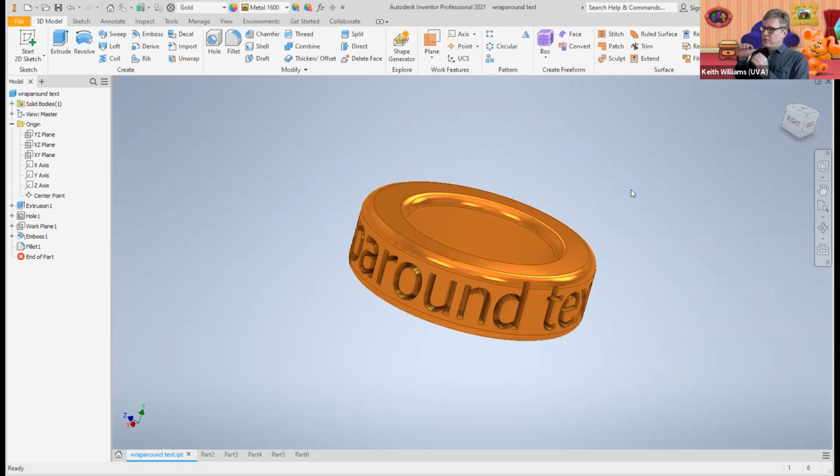The way the 3D printing process works, you put down one layer at a time, and we need to tell the printer what each of those layers is. So we need some additional software, not Inventor or Fusion, that takes our CAD model and does sort of the sushi slice on it, slicing it really nice and thin. And then we send those layers to the printer, and the printer prints them out.